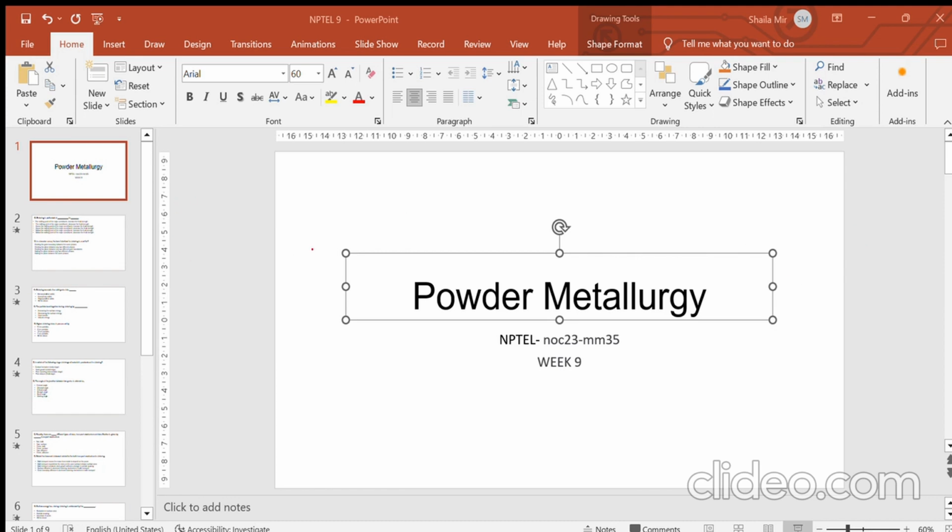So we will have a decrease in the surface energy when you are going through sintering, because these two particles will come together through their boundaries, and their surface energy will be decreased. Okay, you know that when you have a very large number of solids present in the structure, then the surface energy is very large. But if you have fewer particles or fewer surfaces available, then the surface energy will be less.